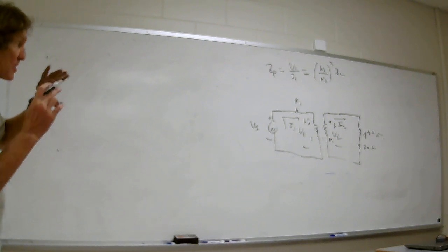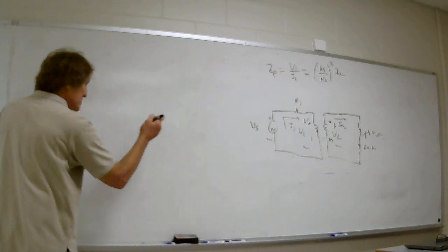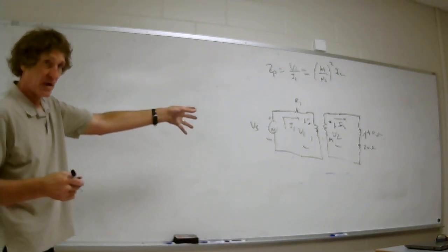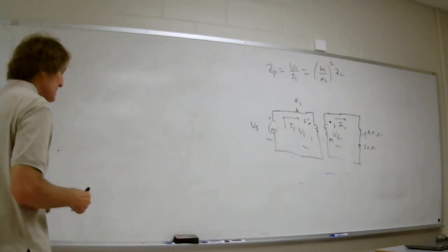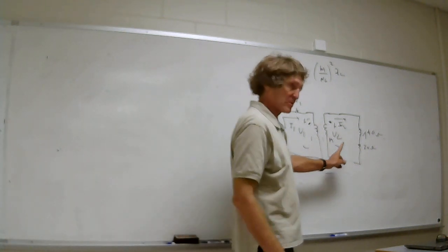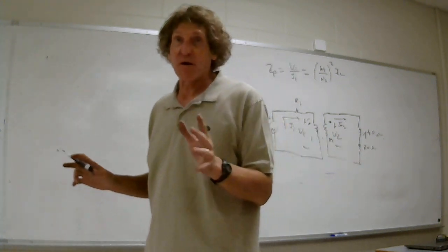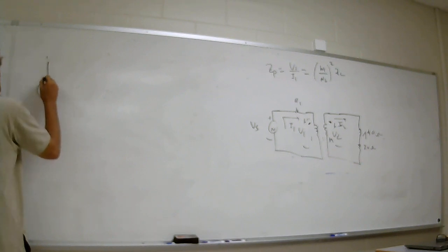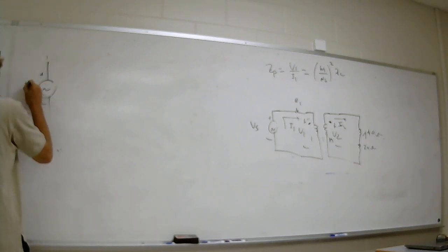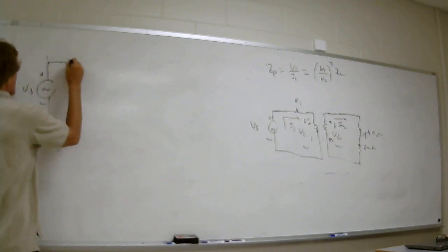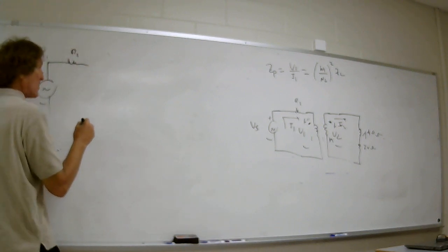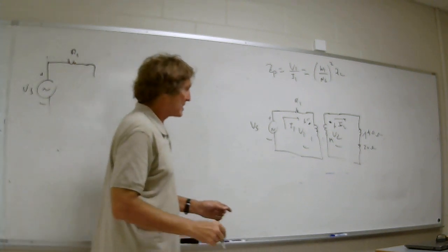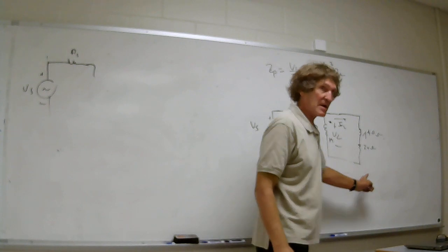If you look at this, go to the primary side, that's this side, and just replace that transformer's effect in that load with the squared turns ratio, okay? So what happens is, remember, there's 1 to N turns. So I've already got rid of the problem of N1 over N2. So over here, your primary circuit looks like this. Then I still have the resistance R1, right? Now I come over here, and I put the equivalent impedance, which is going to be this load divided by N squared.